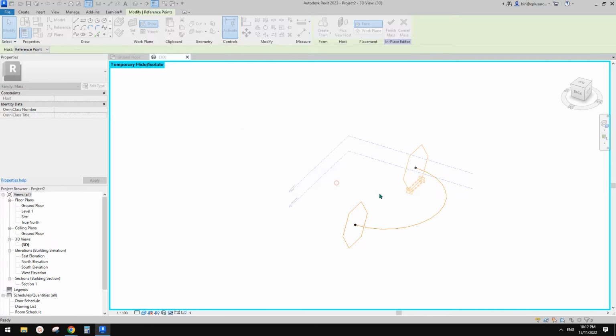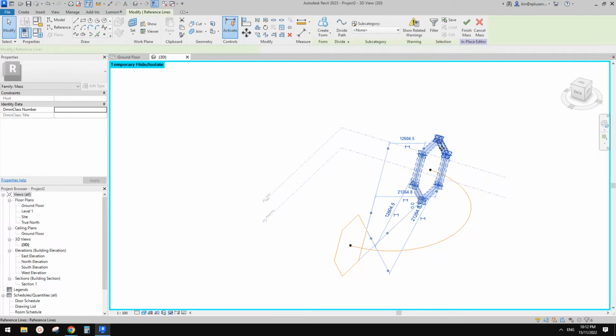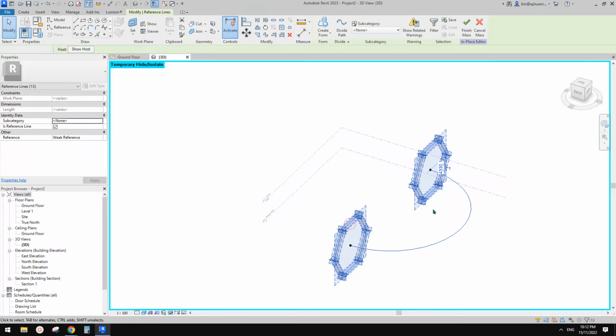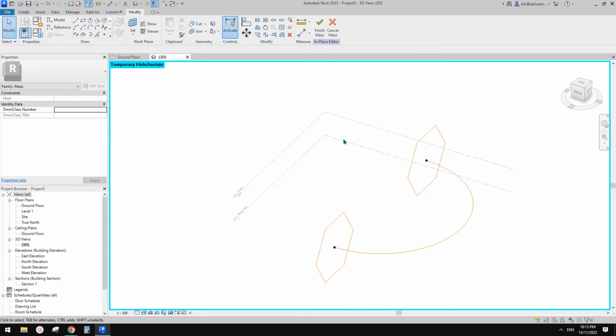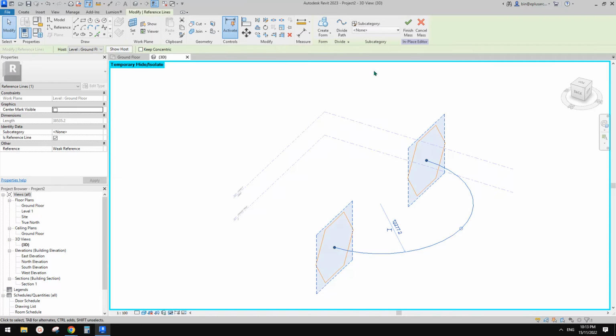Okay, it's fine. So let's click OK, and then we can select this and this. Hang on. When we select this path, try to tab, because although this part is invisible, you might still be picking this part. So let's just tab. Yeah, I think that's good. There's a no filter, which means you only picked one element. So see here. Okay, so good.